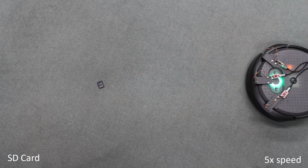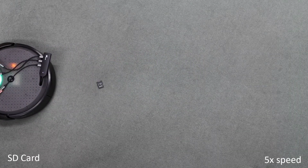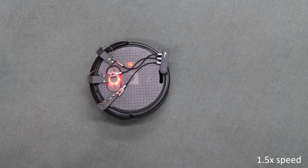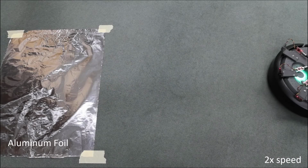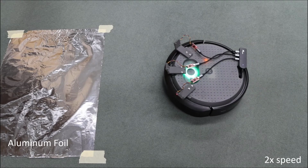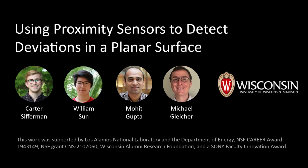There are some situations where our method fails. If the object is small, the sensor may not detect it. If the threshold for detection is set too low, the robot may stop when no obstacle is present. Lastly, if the robot encounters a surface much different than that which the surface model is fit to, it may stop, as the change in surface photometrics means the sensor measurements no longer match what is expected from a planar surface. This demonstration showcases how our method can be used to enable obstacle avoidance and cliff detection in a lightweight, low power, and low compute form factor.